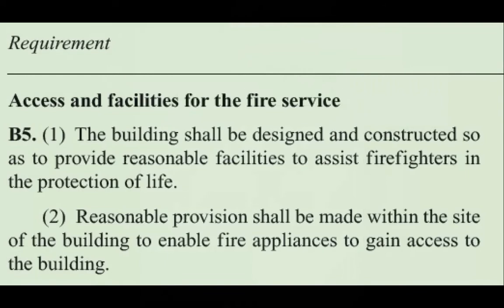And that's why you can comply in any way you want. As long as you're complying with this: reasonable provision shall be made within the site of the building to enable fire appliances to gain access to the building. So basically, can the fire service get to your building? That's what you're looking at. The rest is guidance.